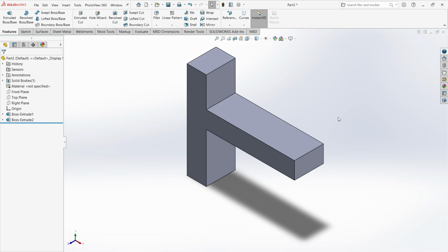Okay, so one option is to create multiple parts like this in real life and perform the force analysis, but that will cost a lot of money. The second option is to use the software, where you can virtually make the part, apply the force and calculate the results. At the end of the static simulation, we get the stress generated, the displacement, maximum displacement, the factor of safety, and the strain analysis. Then we can change the material type if the results are not safe, and if they are safe, then we can manufacture this part in real life.